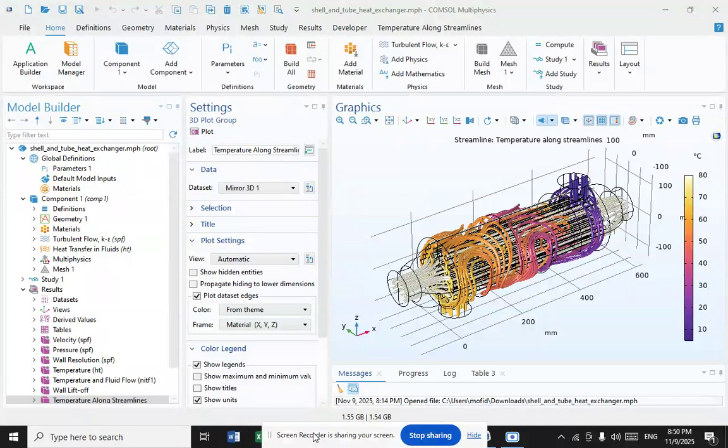In the nuclear power plants called pressurized water reactors, special large heat exchangers pass heat from the primary reactor plant system to the secondary steam plant system, producing steam from water in the process. These are called steam generators. All fossil fueled and nuclear power plants using steam driven turbines have surface condensers to convert the exhaust steam from the turbines into condensate water for reuse.